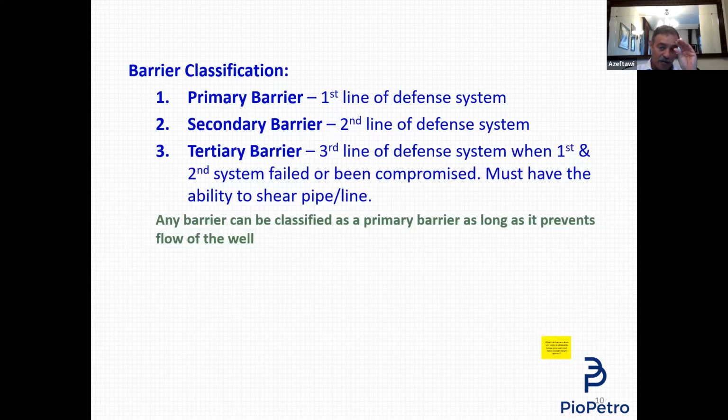So now we have the Christmas tree. We have our equipment on top of it, including our pressure control equipment. We test the whole package to 5,000 psi. Everything went okay. We start running in the hole with the E-line, electric line, that has the shooting guns, perforating guns.